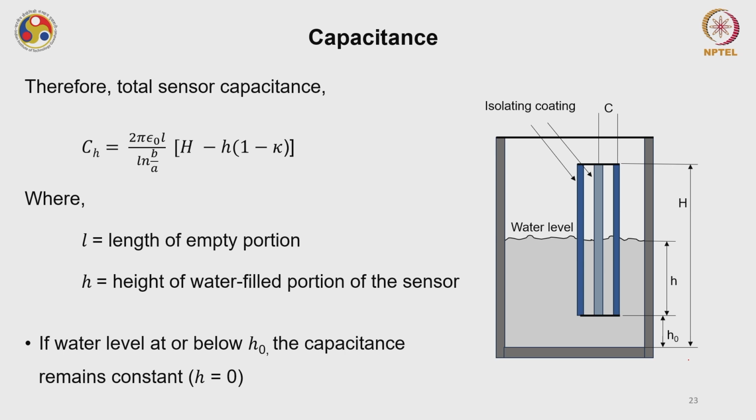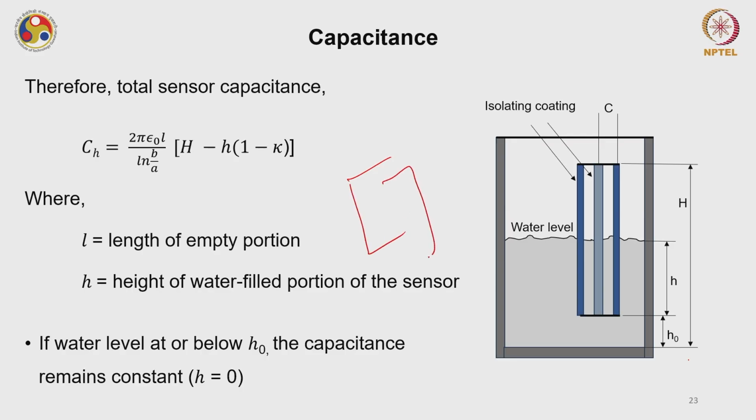There are other sensors also which you can design based on this change in capacitance. This is just one example. Now let me give you an example of humidity, because as I have mentioned, 75% of humidity sensors are based on the capacitive principle. Say consider the same interdigitated kind of electrode. It will look like a planar geometry.